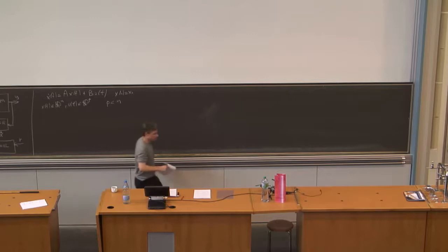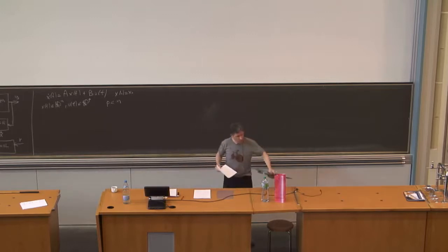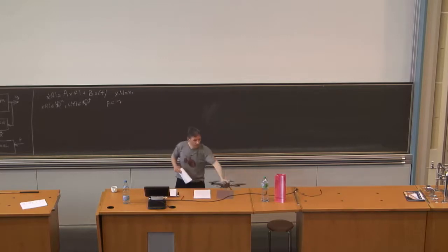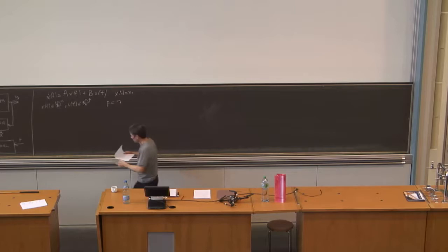Okay, this is what makes the problem interesting: you have fewer control inputs than you have states. For example, for something like this, a quadcopter, which I'm going to do a little bit of theory on in the last part of the lecture, and we're going to do a demo later, has 12 states, right? It has 3 position, 3 orientations, and their derivatives that constitute the system state. So you have 12 states, and you have 4 control inputs, the thrusts of the 4 propellers.